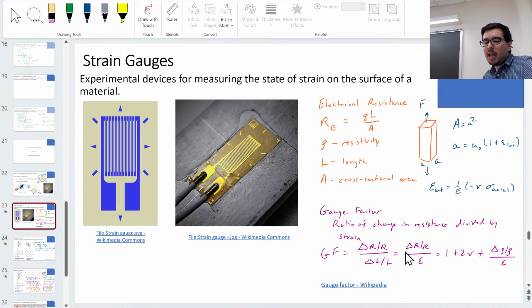What's happening here is there's a piezoresistive effect on top of the electrical effect that you have just with the resistivity, and you see that this thing goes back and forth a number of times, because if I just have one length, essentially this is trying to multiply the effect. So theoretically, yes, but you're going to have a lot of noise probably, electrical noise in that type of system. But that's an interesting idea.